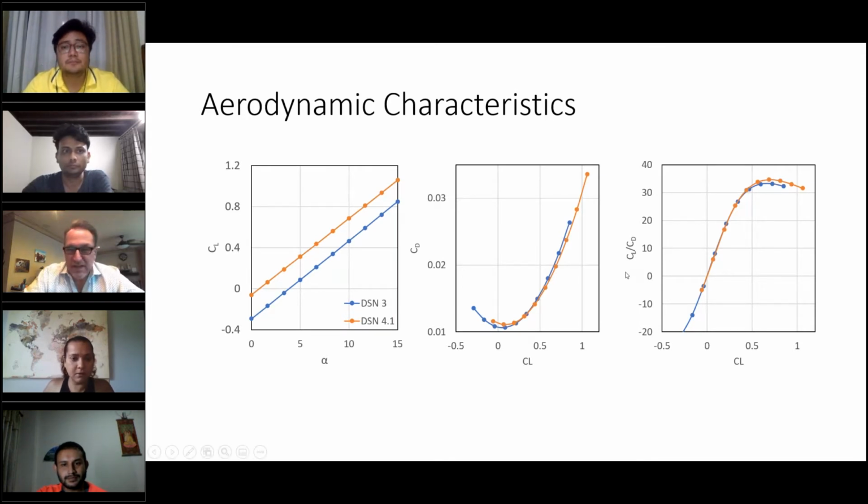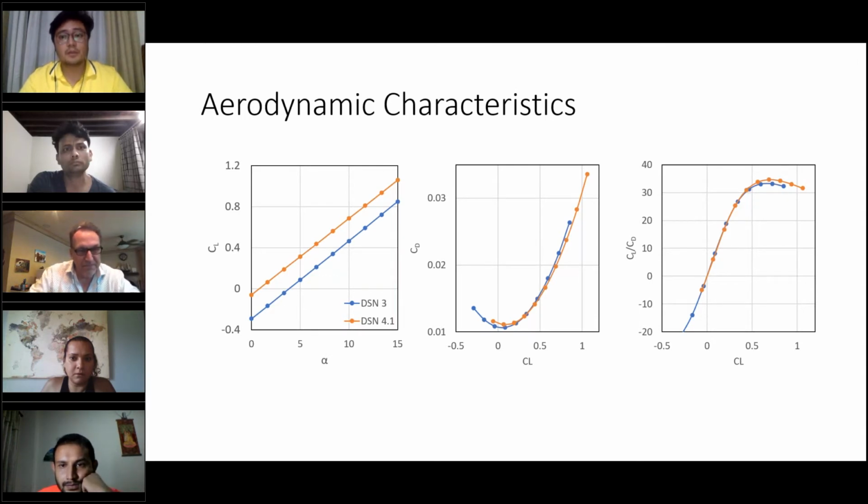Yes, sir. Just a quick question. With these changes, you've preserved the trim. So the pitching moment has been trimmed out at the nominal design lift coefficient. Is that the case in the optimization? So it was optimizing both for efficiency, but also while respecting trim. Is that true?